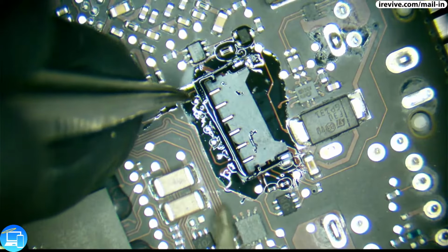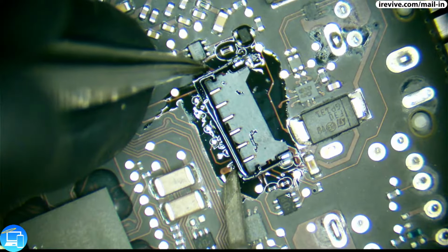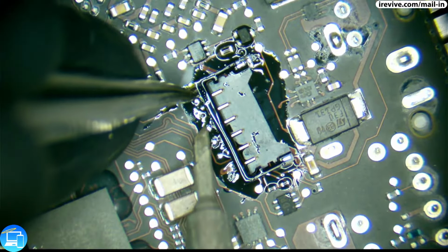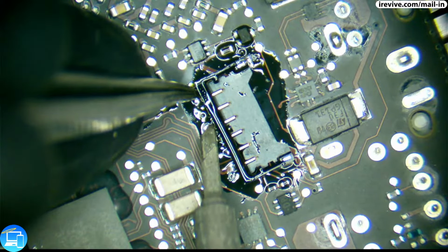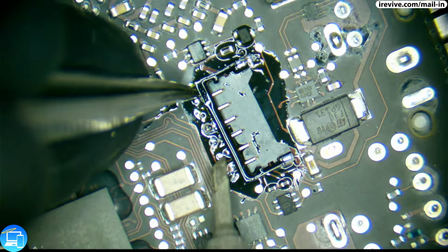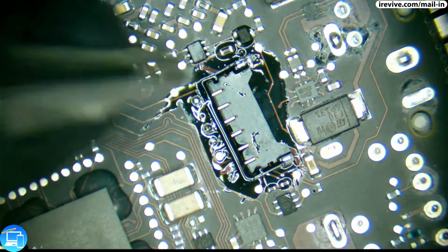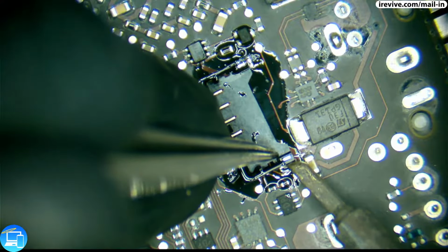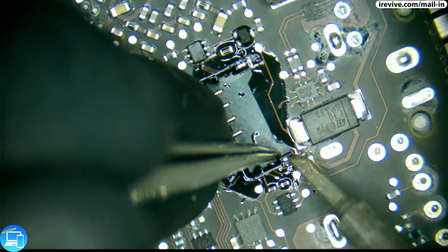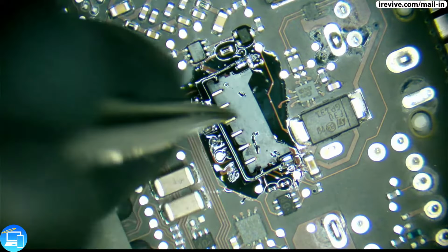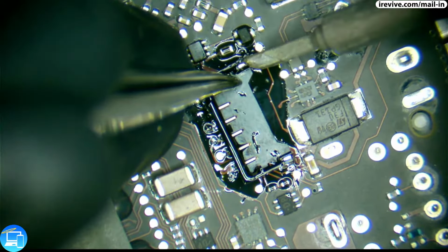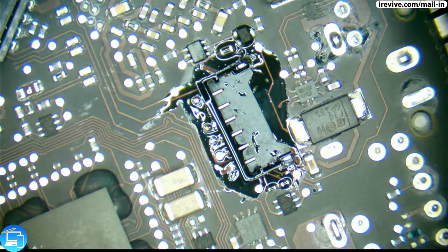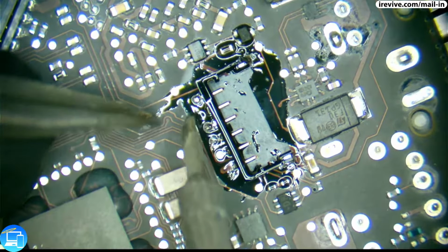I'm actually going to go ahead and try soldering one of these pins down just to hold the Molex adapter in place. These pins are going to melt so much easier because they're not ground, so they don't need as much heat. Okay, so now those pins are down on the Molex connector. Let's go ahead and just start melting the solder here for the ground points. Same thing here. And then just briefly touch up the pins on our Molex.